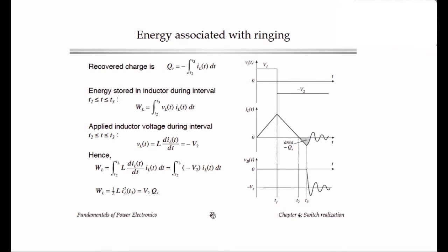And in this particular case, we can actually calculate how much energy there is. The recovered charge, which is the area under the curve, is defined as the integral of the current during this time, as usual. So the recovered charge is a property of the diode. You can also calculate the energy stored in the inductor during this interval. Basically, if we integrate the voltage on the inductor, its negative voltage, times the inductor current, that's the integral of the power, which is the total energy stored in the inductor from here to here.